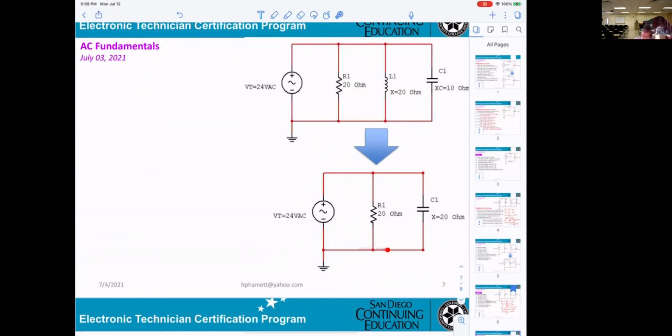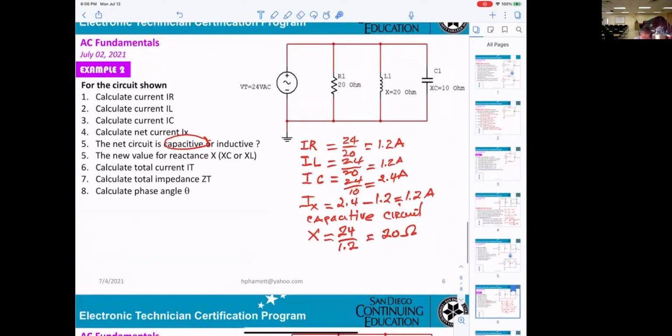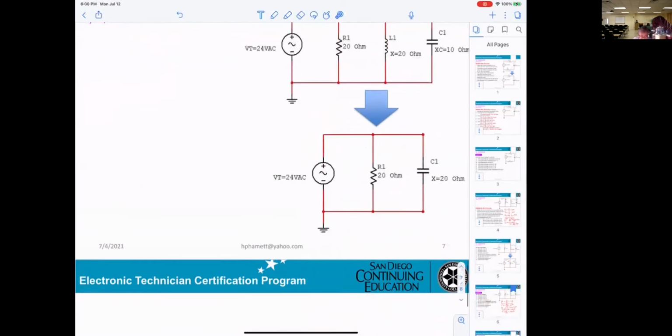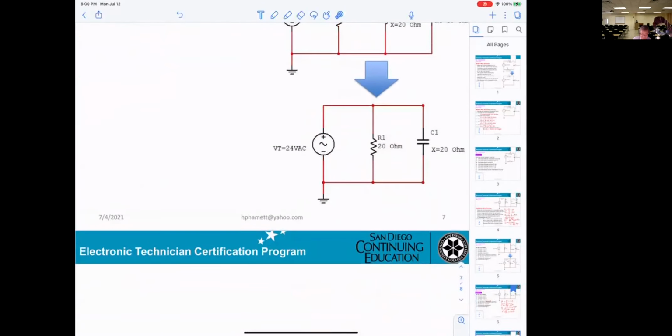You come up with the RC circuit in parallel. And now whatever calculation you want to do, go to the RC circuitry. Then that will help you to get whatever you need. Like they say, they want to calculate the total current and the total impedance. If you want the total current, it will equal the square root of IR square plus IX square.